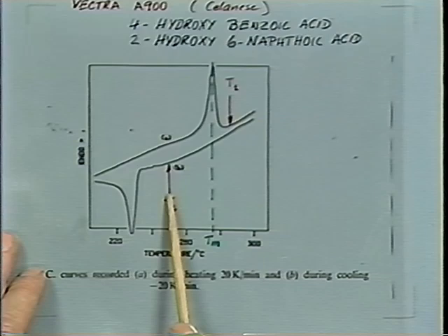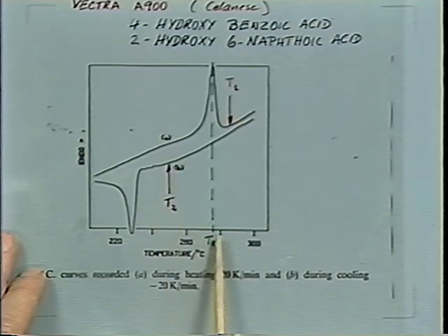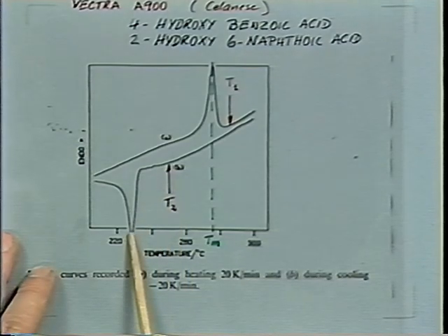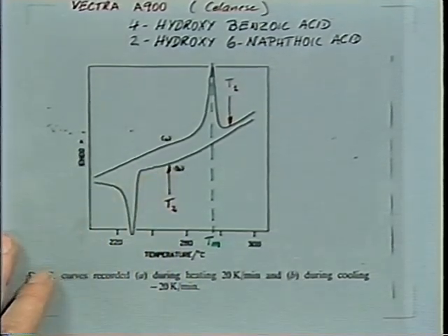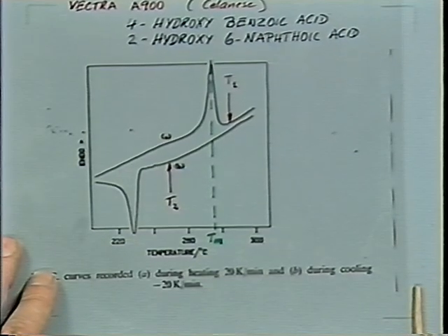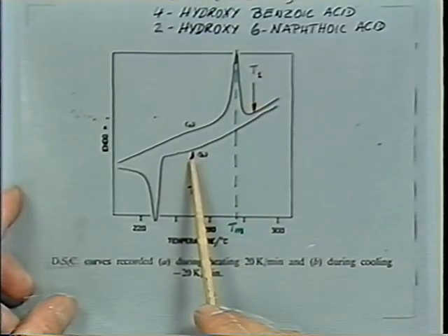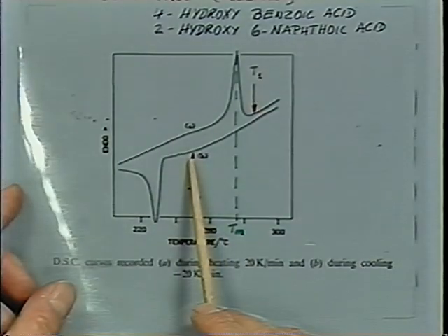You could probe the material at temperatures much below TM. It will show liquid behavior, and then if you go deep enough, quenching deep enough, you will find the solidification. We'll see the solid behavior coming in. We will look at a few data in the beginning where we go to a very low temperature, we heat up the sample, and then we look at the rheology in the supercooled state. The material will not stay liquid in that supercooled state for a very long time.